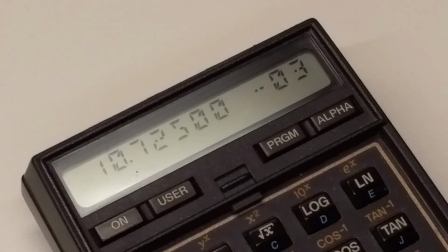Now, it's not quite as easily done in general for arbitrary values of inductors that you want to measure, because the ease of making this measurement depends on the Q of the inductor. And you might imagine that for very high or very low quality factors of the inductor, that null might be more difficult or less difficult to find. So this is not a panacea.